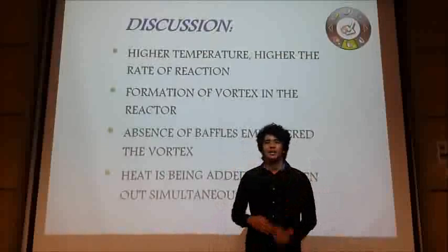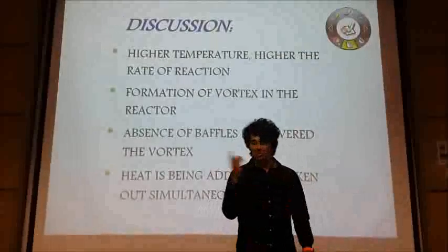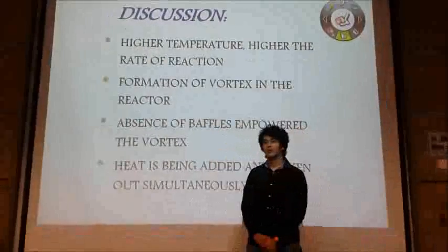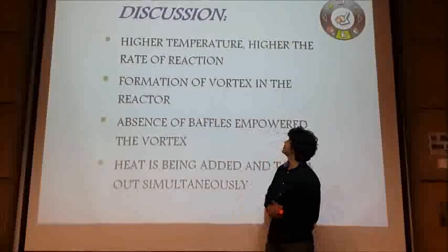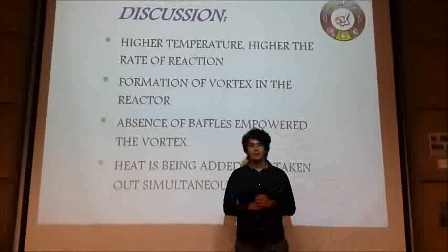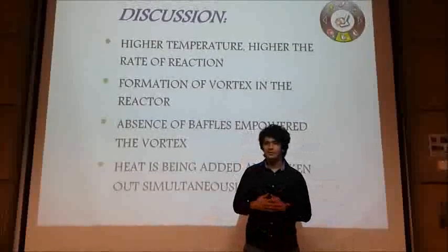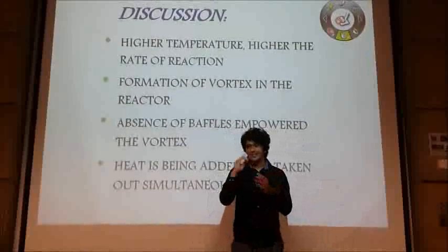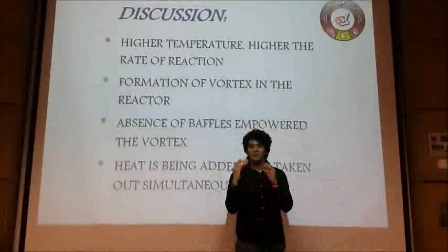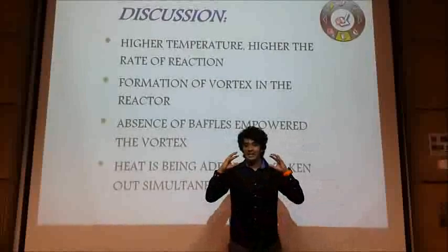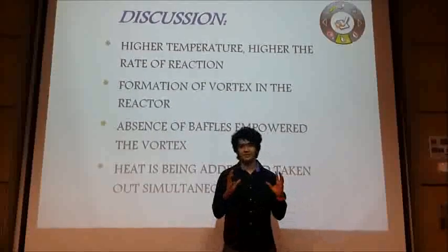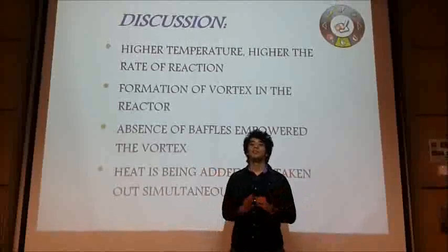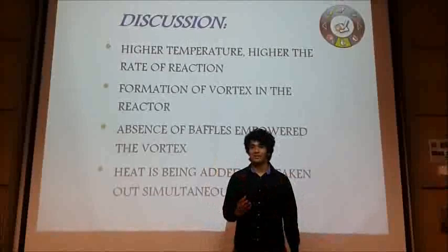Now, what is a vortex? It's a whirlpool of fluid or air. It creates a spinning motion. This spinning motion will create unreacted regions in the reactor. So that's why the reaction time will actually be longer with the formation of the vortex.